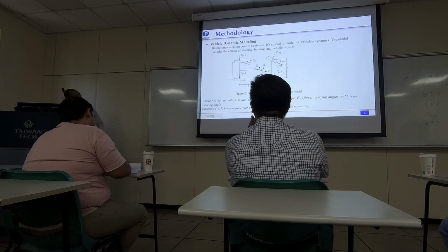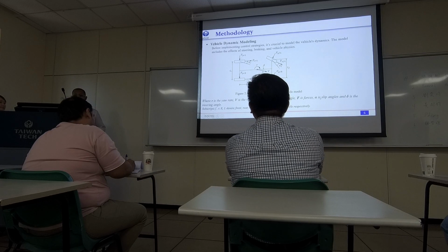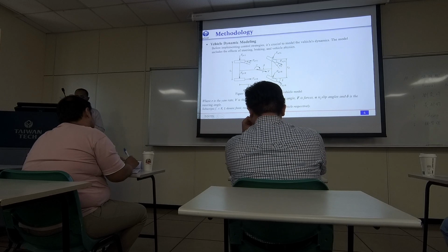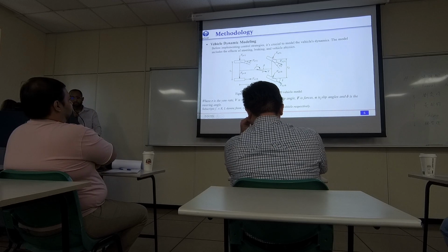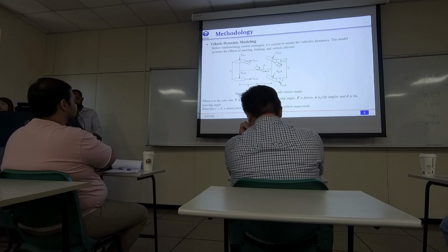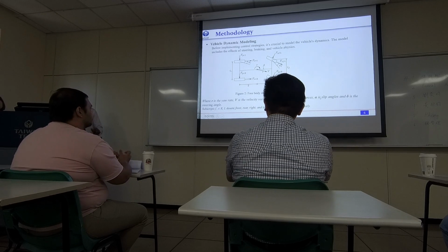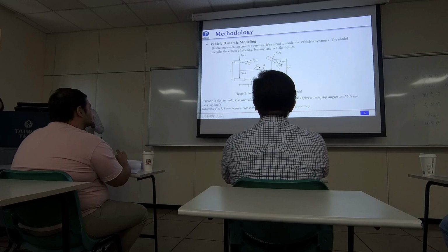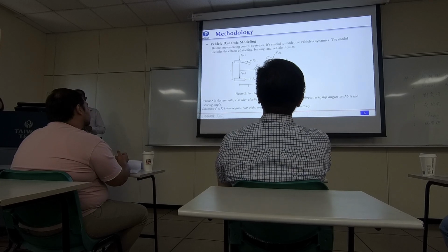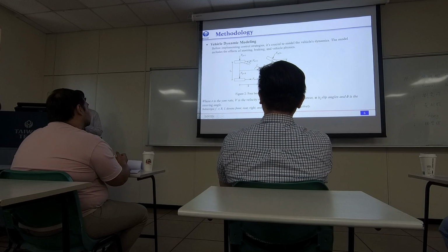Okay, so I will continue to the methodologies, how we will tackle the problem. First, to optimize the control action, we have to model the vehicle dynamics using a 4D vehicle model. Basically, in the 4D vehicle model, we use the lateral and longitudinal, yaw and roll motions.